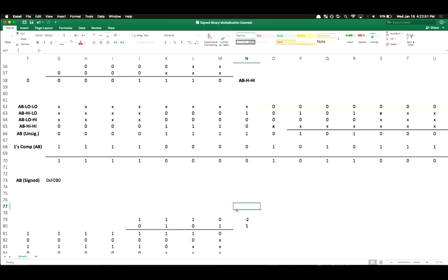I'm just doing a smaller example because doing 32 bits would be way messier. So I just did an 8-bit times an 8-bit, splitting it up into 4 4-bit multiplications. How is 16 split to 8? Exactly. So for you guys, you have a 16-bit number times a 16-bit number, but those are split up into 2 bytes in memory each. So this is emulating the same thing, just with 4 bits.